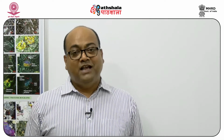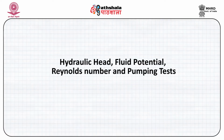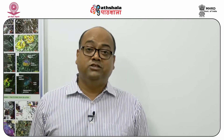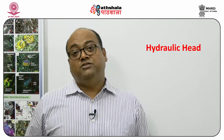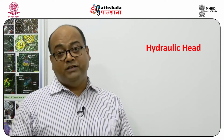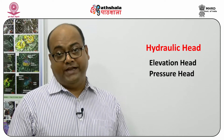In this module, I'm going to talk about how we measure hydraulic head in the field and how the measurements of hydraulic head and the differences in hydraulic head are used to measure important hydraulic and hydrologic properties of different aquifers. So in continuation, I would first like to say that hydraulic head is basically the sum of two components. One is the elevation head and another is the pressure head.